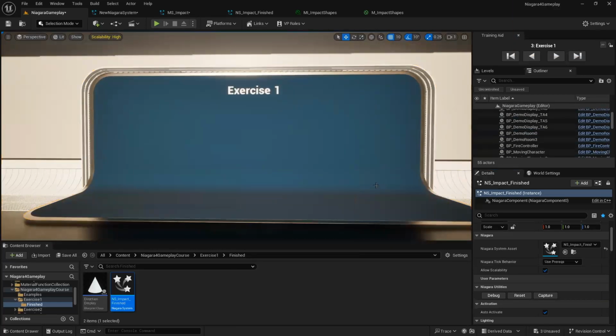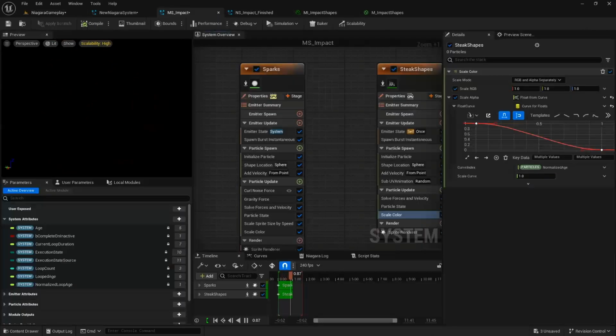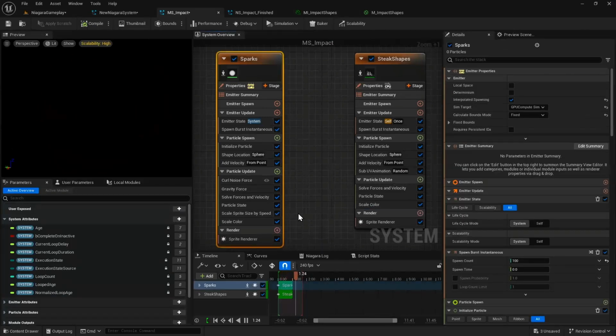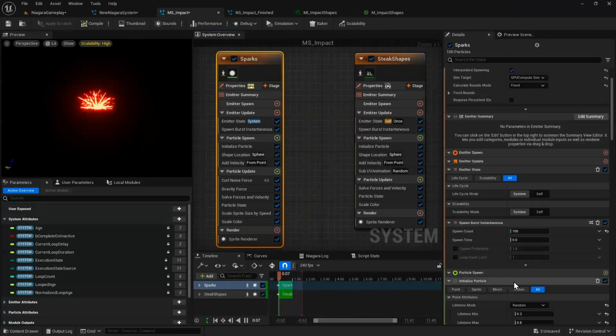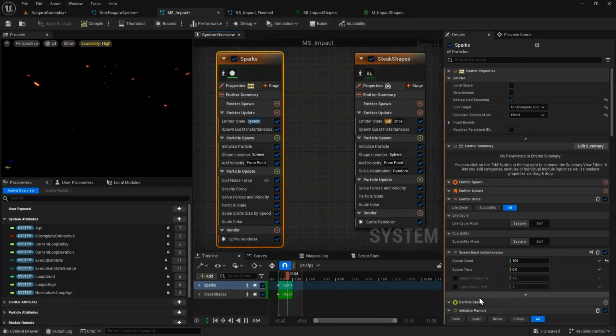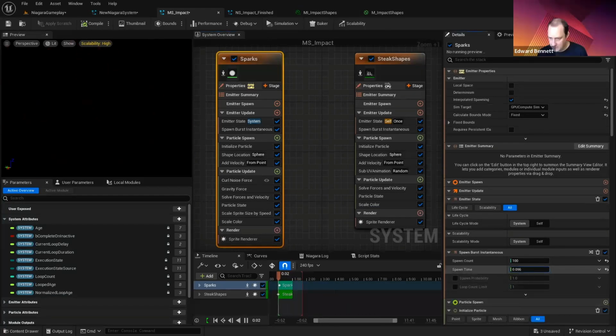Some people sparked emit with a delay, but that's probably going to be down to spawn time or your emitter delay. You just select your emitter and check for the delay itself. Spawn time 0 is probably what you want at the sparks. If you move it to 2 seconds, it will delay.